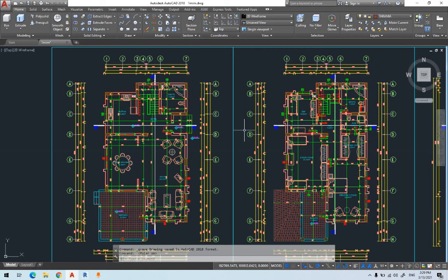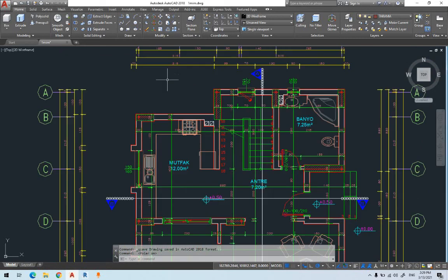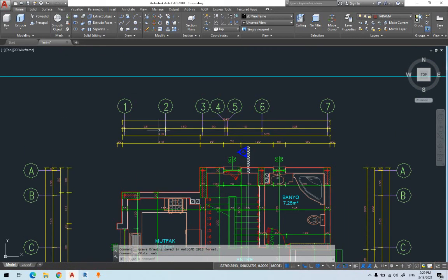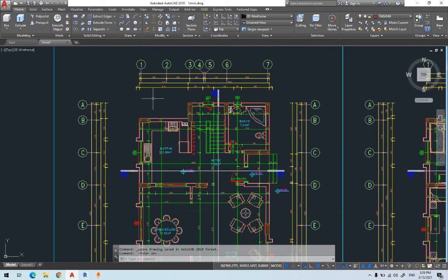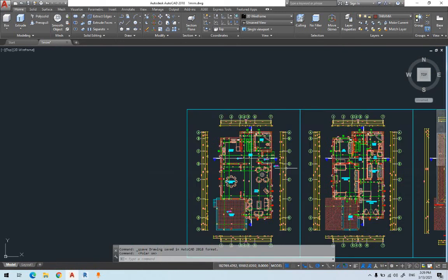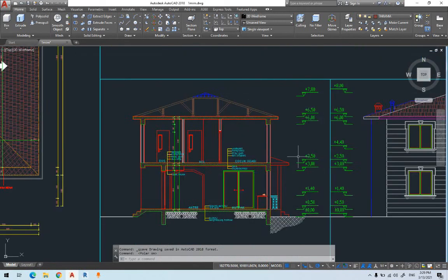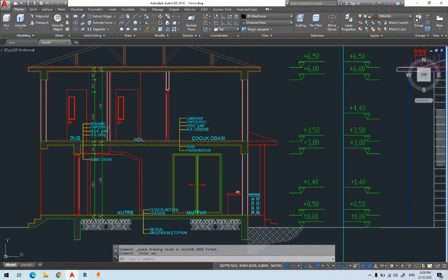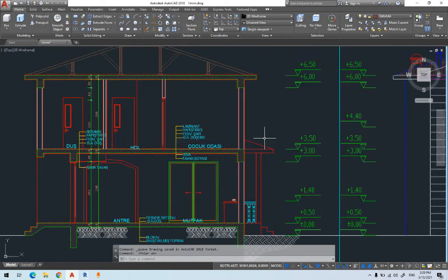Now, to do this practice, we have this example. So we say the first thing is to read the grid lines and construct them in Revit. Now the grid lines are easy to be seen here. However, for the levels, we say we're going to look at the sections. So for this project, since we're trying to add columns, usually columns start at the top of the foundation till